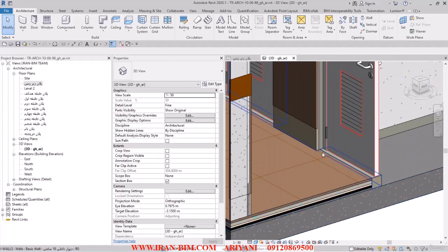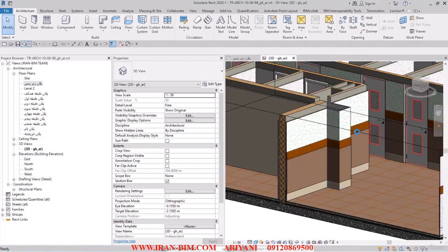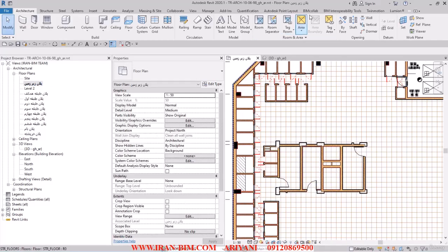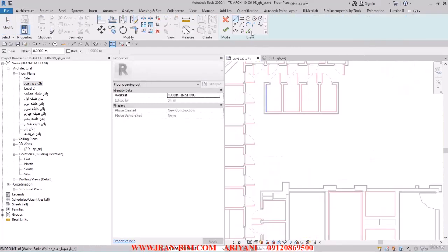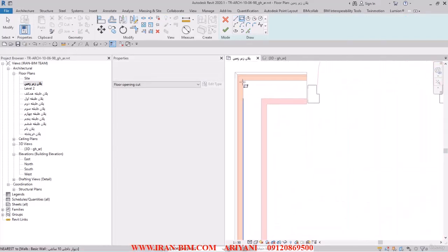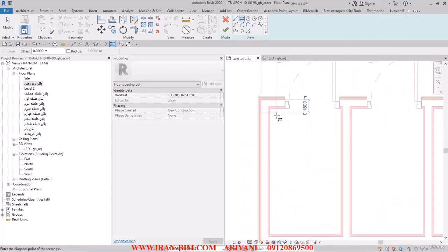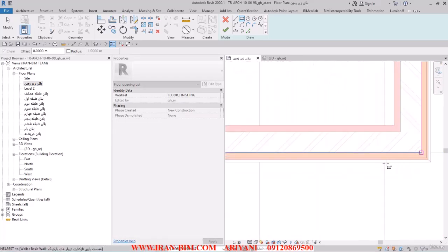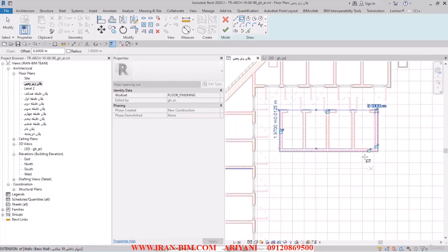And now we're going to go to the underground planning. And now we're going to be emptying out this area in the middle, like this part here and this one as well. So here I'll choose this vertical, and then I'll click on the floor here. Here I'll select the rectangle tool, and I'll draw one from this point here down to this point here. After that, I hit the finish.